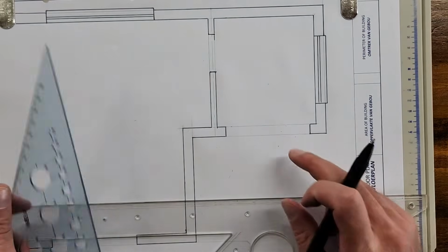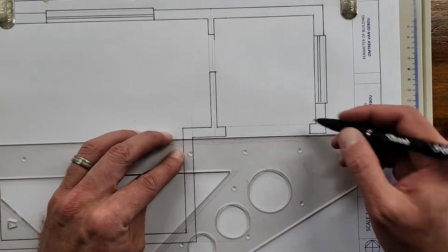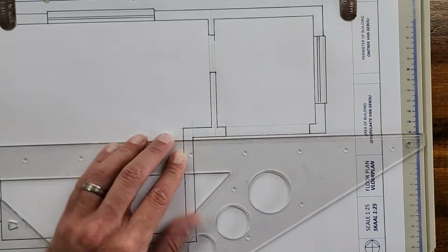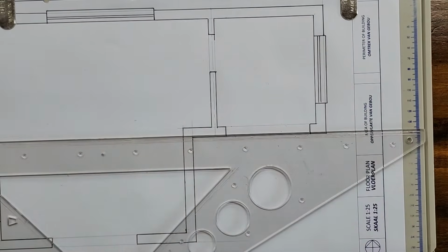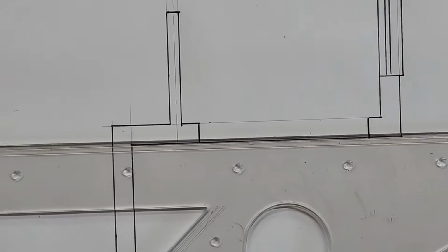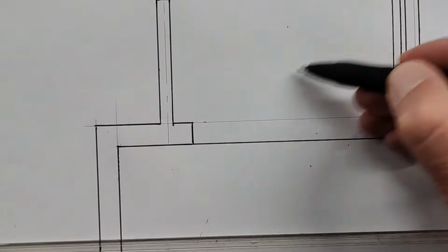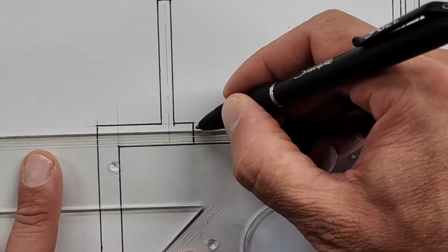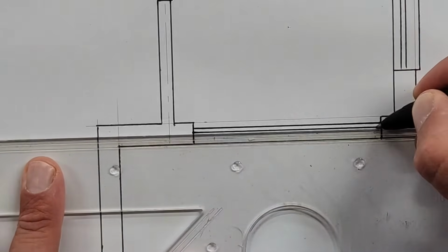Okay, there we go. For our different doorways, D2 is a sliding door. So first thing, when it's on the external wall, there's a step there. That's a straight line going all the way through. And then the sliding door, maybe let me zoom in here for you to follow me. There's a sliding door. This line is the step from the finished floor level on the inside to the natural ground level. And then we have two lines similar in width.